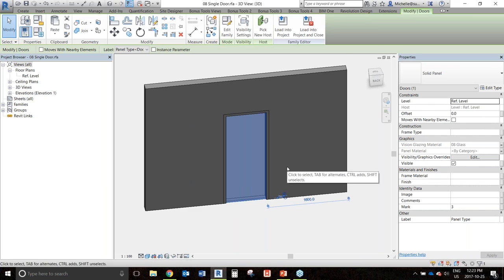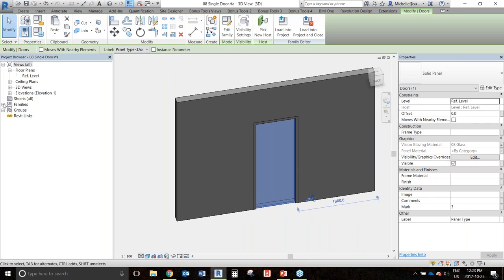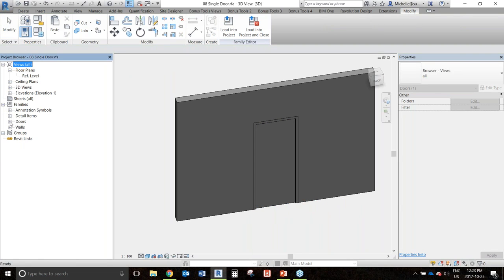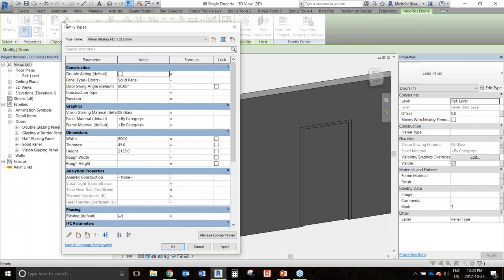Now, the other thing I wanted to talk about, which is nice with nested families, is that you can add a parameter to the family itself. So this is really handy if you want to be able to switch out one panel for another, so one family for another. So we want to add a label to it. This is the same way you add a label to dimensions, materials, anything like that. So you add a label, you call that the panel type. And then because I've nested in here a bunch of different panels, what that allows you to do is switch that out as a parameter.